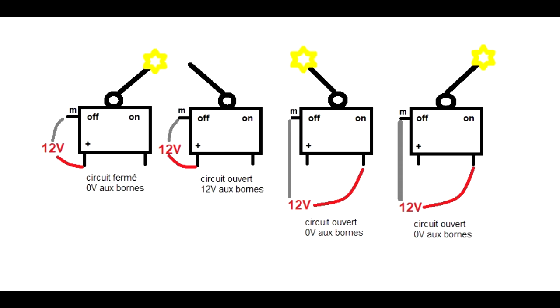So that is not good for the LeoBodnar board, but it's good visually. On the right, it's good for the LeoBodnar board because there is no voltage on the pins, but the light is always illuminated. To make it work, we're going to use the left option, and we will use a relay to isolate the 12 volts from the LeoBodnar board.